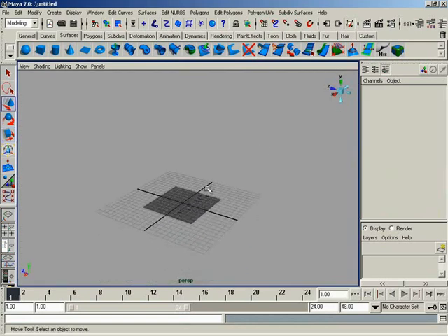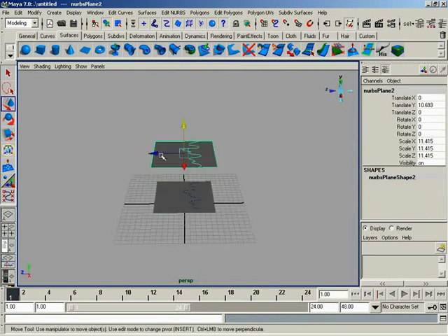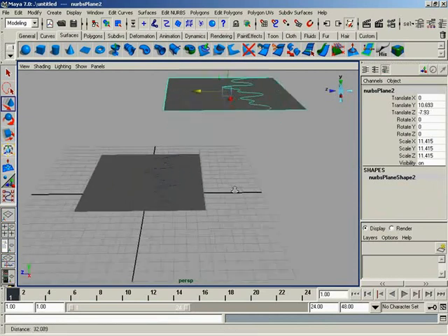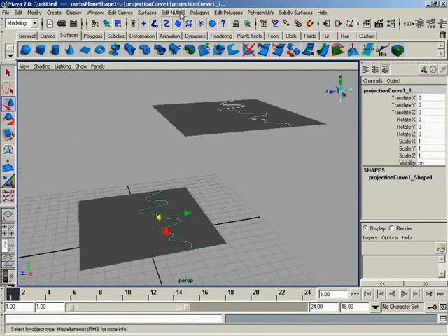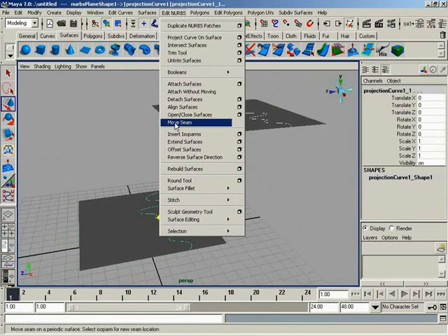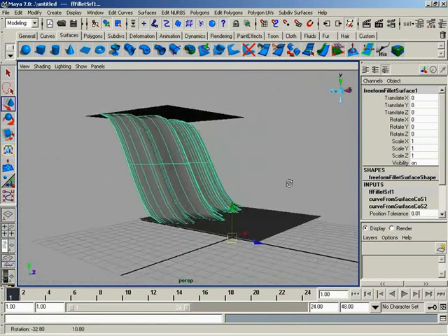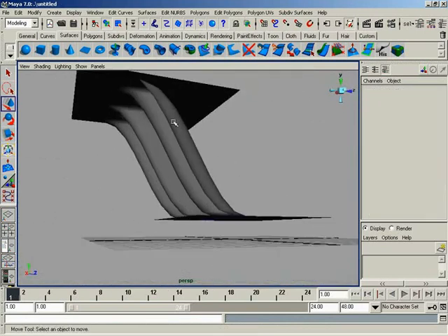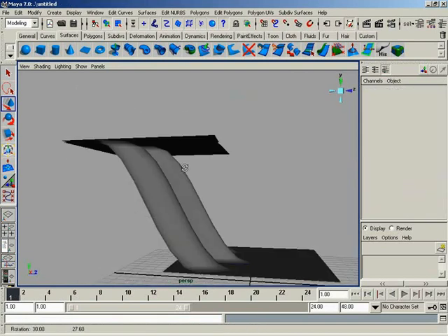And let's just make a duplicate of this plane. So we'll move it up, Control D, move it up, and then I'll slide it off to the side so we have a little bit of tangential direction we can work with. Now I can grab this curve on surface and this curve on surface and do the exact same thing I did before. We go to Edit NURBS, Surface Fillet, Freeform Fillet, and we get a nice freeformed fillet shape that goes right in between those curves and tries to follow as best it can the tangency of the two surfaces. It looks really good too.